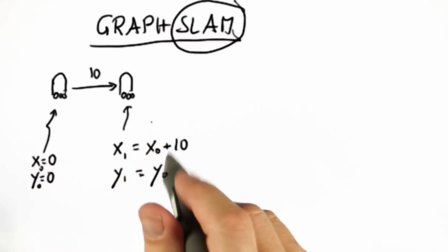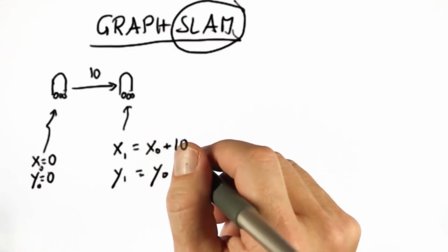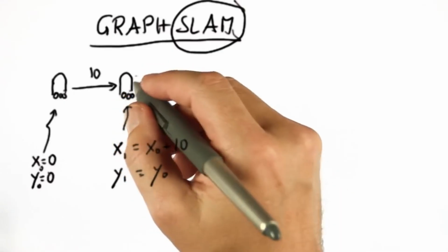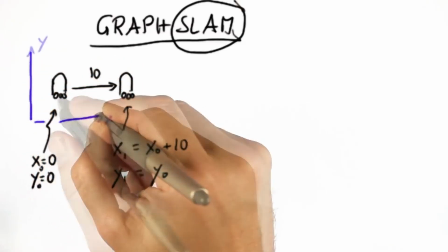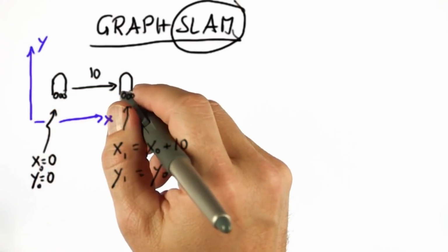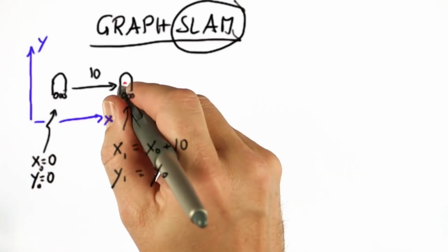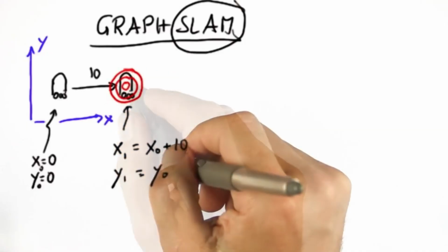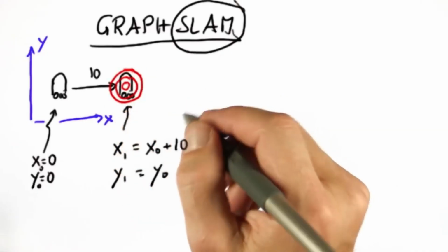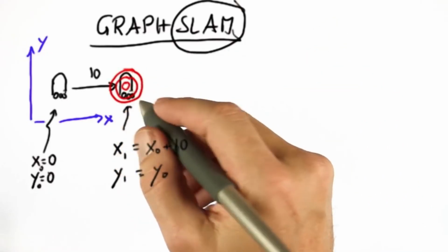But we learned from our various robotic Kalman filter lessons and others that the location is actually uncertain. So rather than assuming in our xy coordinate system the robot moved to the right by 10 exactly, we know that the actual location is a Gaussian centered around 10, 0, but it's possible the robot is somewhere else. Remember, we worked out the math for this Gaussian?